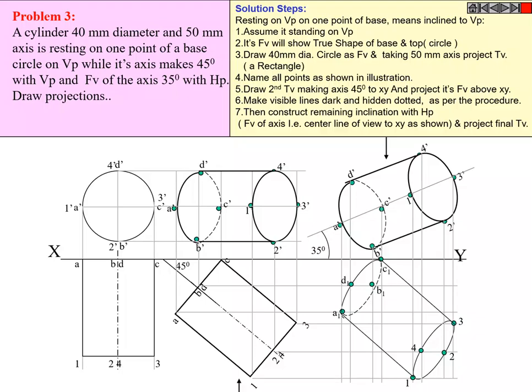Right? So here, if you see from here, this face is completely visible, and the edge which is inside, D dash, C dash, B dash, is not visible, so put it in a dotted line and construct the required shape. Afterwards draw the 35 degree line, place the second position of the front view at 35 degrees, draw the projection lines and get the required points.